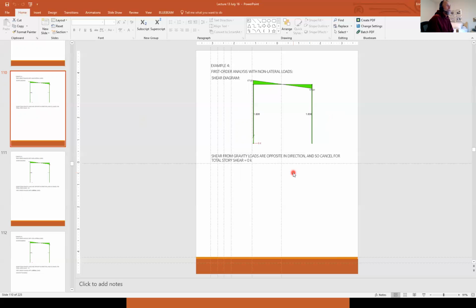Well, one example would be a building that is subterranean by some degree, and you have concrete walls around it retaining dirt. Now the dirt forces are shoving the building over, and you have some shear in your building resisting the load from that dirt. And that load would pretty much be sustained all the time. The dirt would always be pushing up against your building.